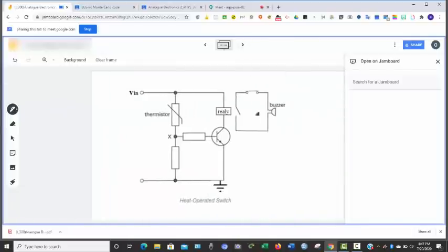So this is when we are using the base voltage, this resistor, and this is what is setting this base voltage. This resistor is protecting the base, because if there is no resistor at this base, it will damage the transistor. So we will do a calculation like what we did before to know the value of the resistor that can be put at the base of the transistor to supply a certain value of collector current. And usually we use 2.7 kilo ohms.